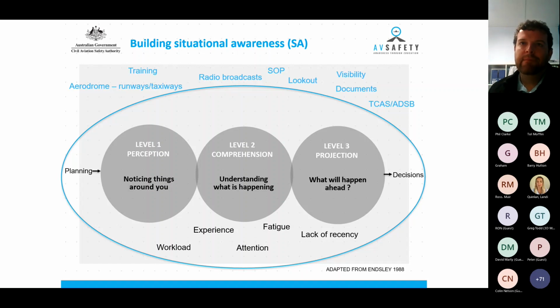So I think Chris mentioned before this whole tunnel vision thing, where you're so focused on one item. Sometimes students are so focused in that 10 nautical mile boundary that they're looking at their fuel. Sometimes they're thinking too far ahead in terms of the forced landing. You might give them an hour from now, but they're not really focusing on the task at hand, which is going to be the most critical safety point of the flight, which is how you're going to manage the traffic when you actually get into that circuit, and planning ahead of what you're going to do in certain scenarios should they unfold. Yeah, some good points.